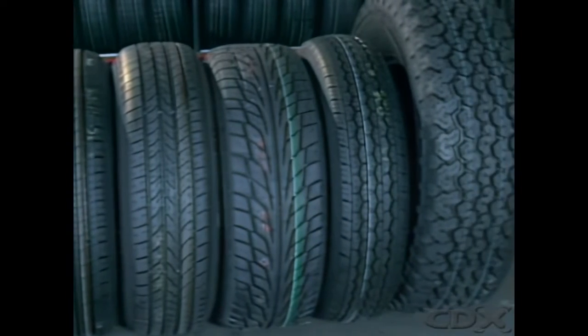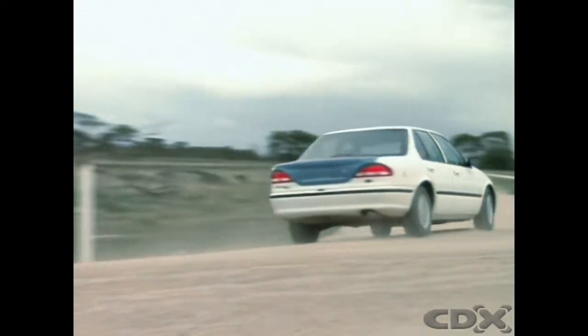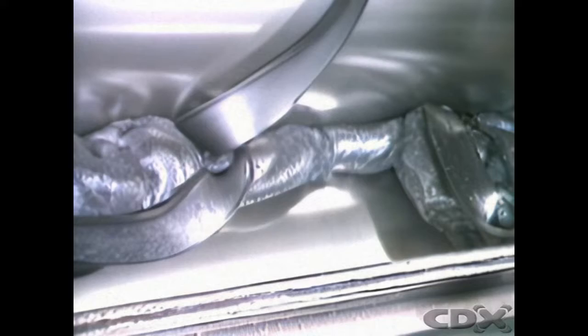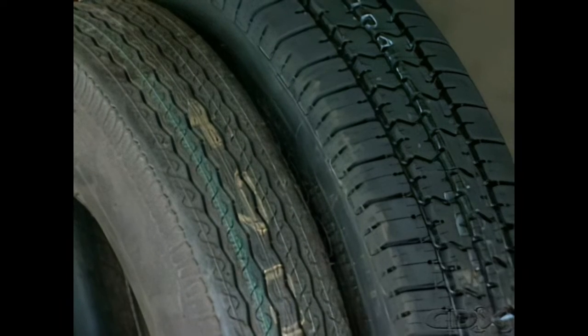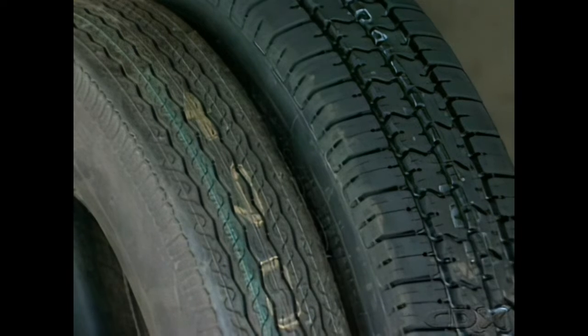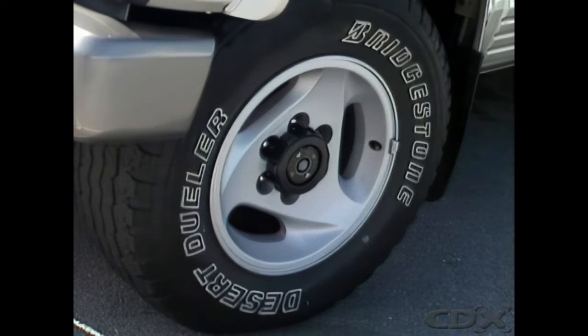The tire provides a cushion between the vehicle and the road to reduce the transmission of road shocks. It also provides friction to allow the vehicle to perform its normal operations. Modern tires are manufactured from a range of materials. The rubber is mainly synthetic. Two types of tire construction are common: cross-ply and radial. Most passenger cars now use radial tires, and radials are replacing cross-ply tires on four-wheel drives and heavy vehicles.